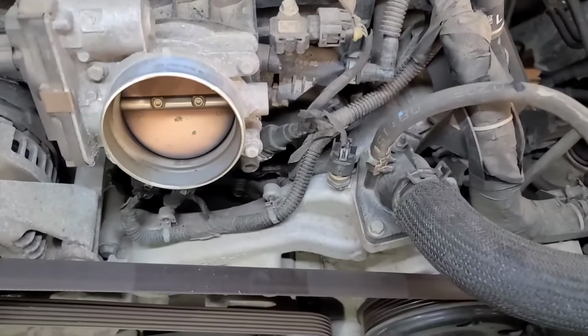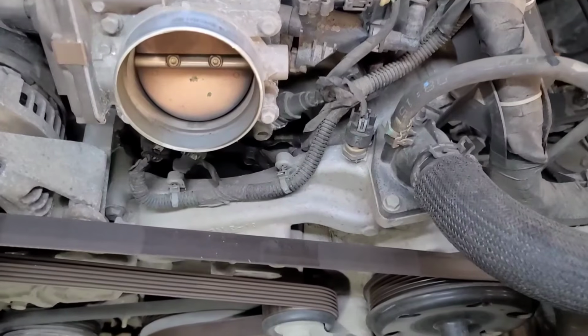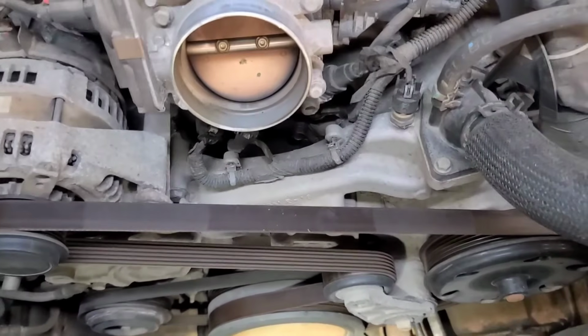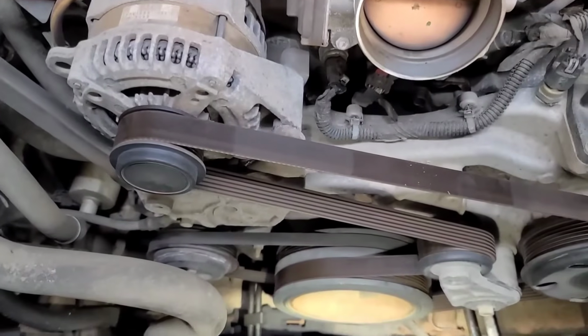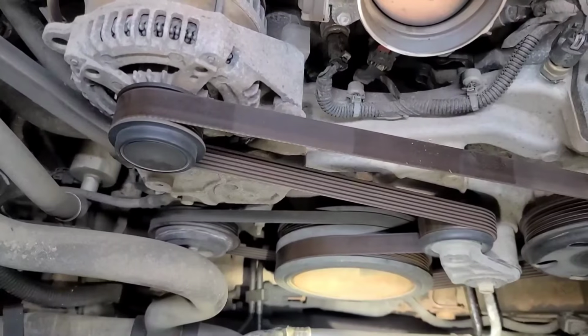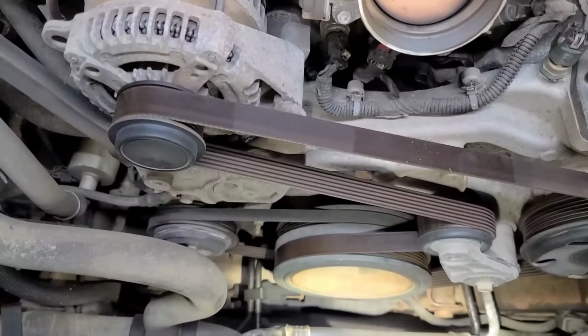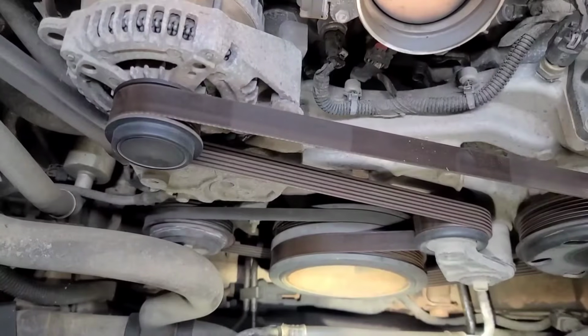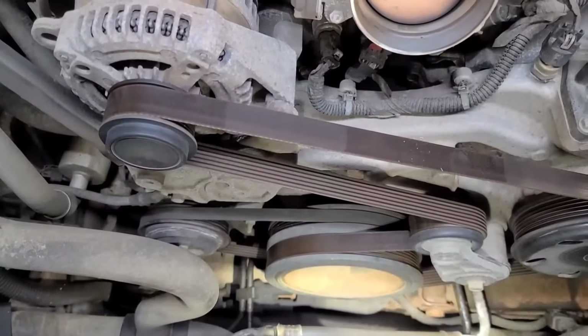Now the serpentine belt has to come off, the whole front of the engine has to come apart because the timing cover has to come off. I see we've got a stretch belt on the AC, so we'll have to deal with that. I get to use my stretch belt tool for the first time, I think. I don't know if the AC compressor has to be moved. I don't think so, but definitely all the front of the engine has to come off.